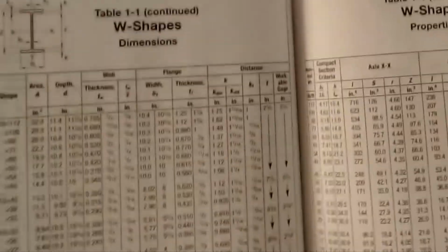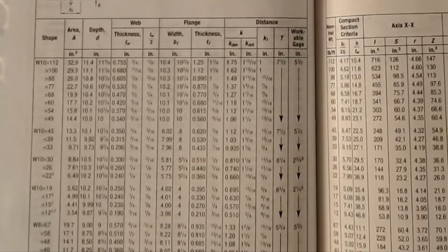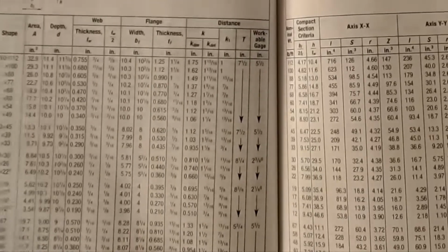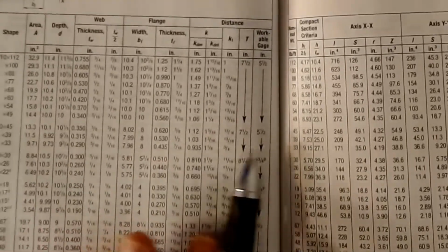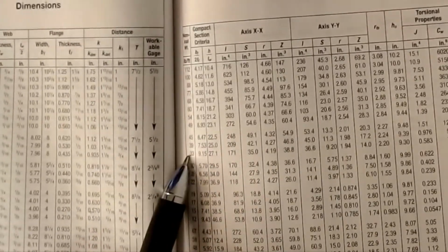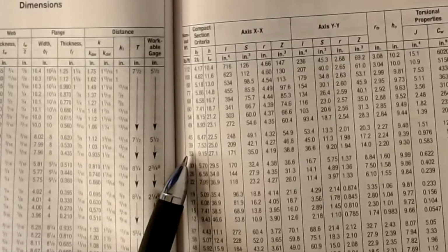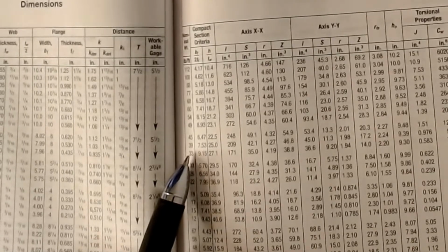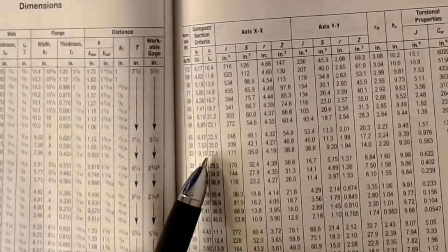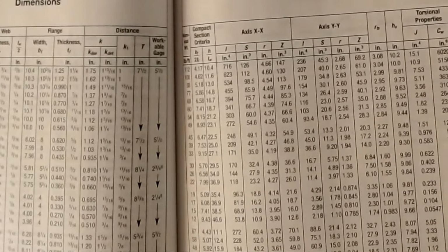Now, the part where this manual really starts to pay dividends is over in the computed properties page, which is on the next slide. So if I look over at my 10 by 33 again, we're looking here, and I follow this line all the way across, and I go over to the next page, you can see that there's this number 33. This is a continuation of the line that we were looking at. Okay, now there are some things that you'll use for calculation. So for beams and columns, when you're looking at compact sections, these two criteria will start to play a role, and these will be numbers that you'll pull out for a shape to learn about some of the section properties and the calculations that we'll show you in some of the later videos.